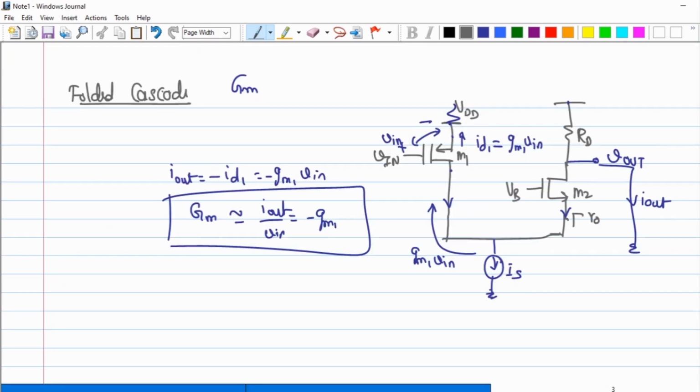Now, had we really addressed the issue of moving this value of VB? That is the next question, because the whole point of going from the cascode device to the folded cascode is that VB was stuck between the value of VD2 and VD1. Now, with this circuit, can I make this VB go higher than the value of VD2? No, right?